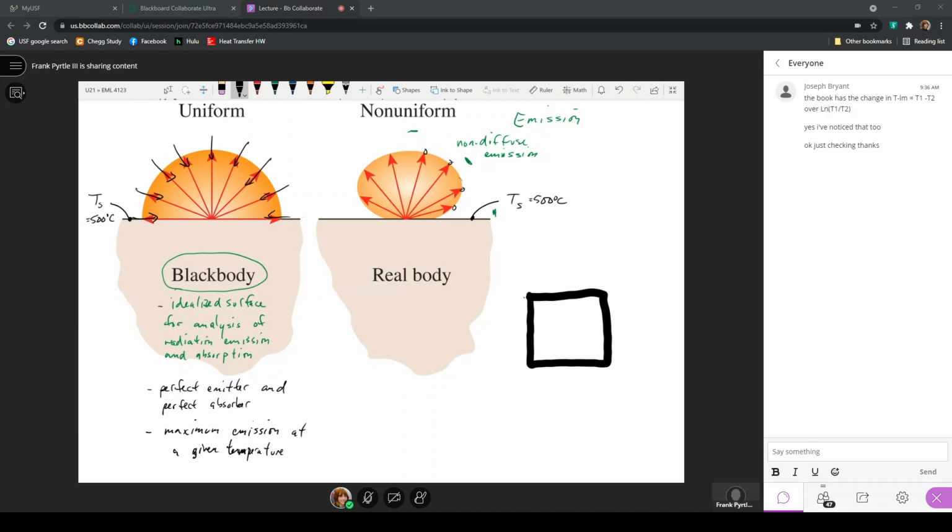But that's a case where that surface behaves like a black body surface for the visible light spectrum. But when we talk about a black body surface, not only does it absorb all visible light, but it also absorbs all of the infrared, and it absorbs all of the upper part of the UV to make up all of the thermal radiation range. So regardless of the wavelength, regardless of the direction from which that energy is coming in, a black body surface will absorb all of that energy.